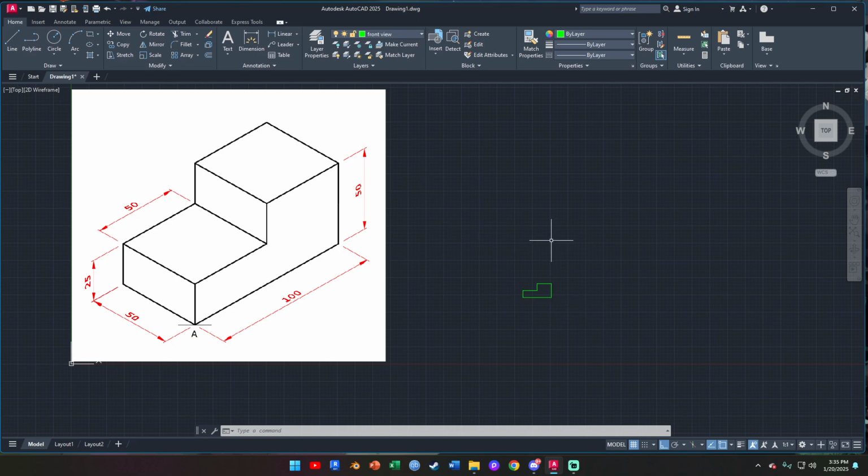So always remember, whether it be cabinet oblique projection or cavalier oblique projection, the front view of the object is always drawn to its full size or full scale. The only thing that would determine the size of the receding line would be if it's cabinet projection or cavalier projection. And seeing that it's cabinet, we're using half scale.